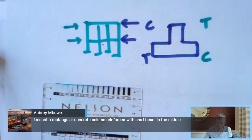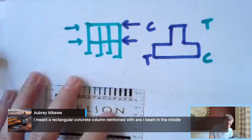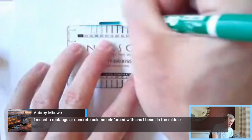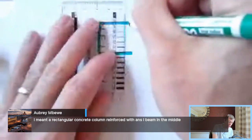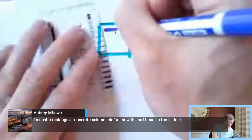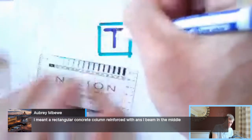So now Aubrey's talking about, he means a rectangular column, is what he's talking about, before this composite stuff with the steel beam in the middle. So rectangular column with the steel beam in the middle. So that is done sometimes on retrofit applications where I have a steel structure that may not be sufficient.